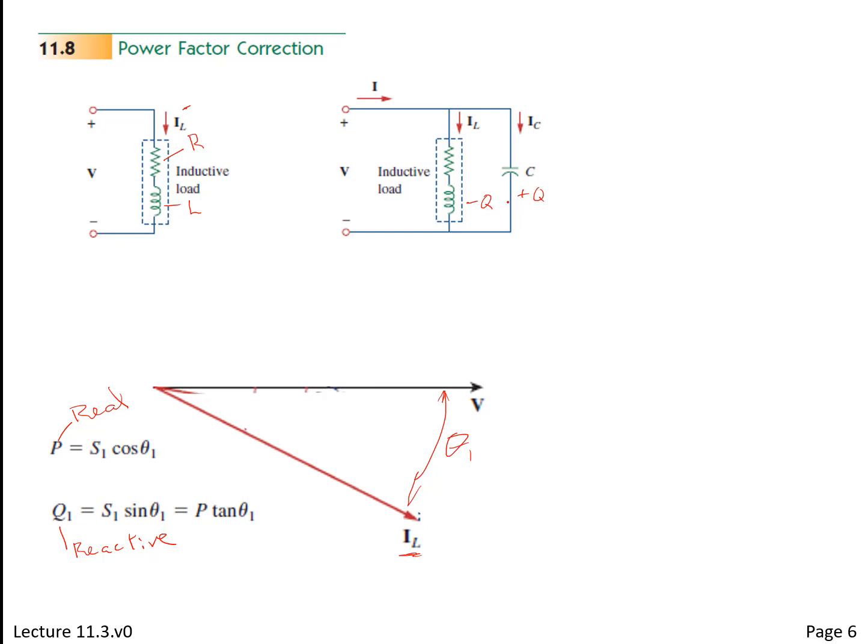And maybe you could call it complement, except that we're talking about power. We don't want to waste a lot here. Well, but we're not trying to make IL 0. We're not trying to make IC 0. We're trying to make the combination of reactive power that both of these consume together go to 0. We're trying to change that amount.